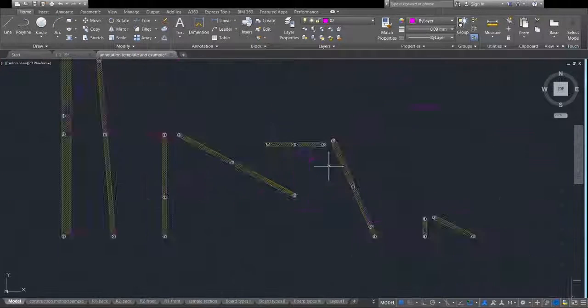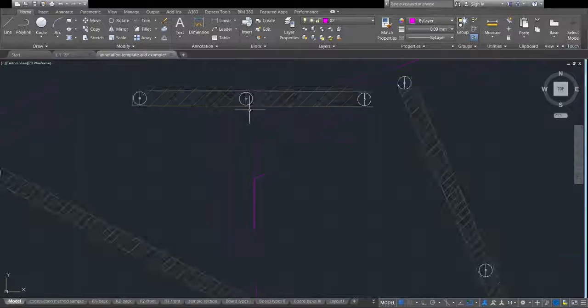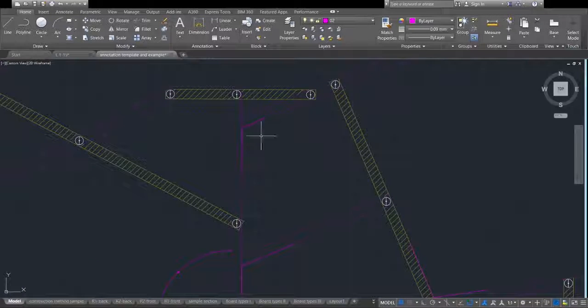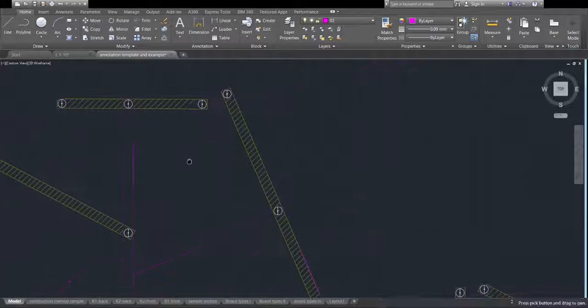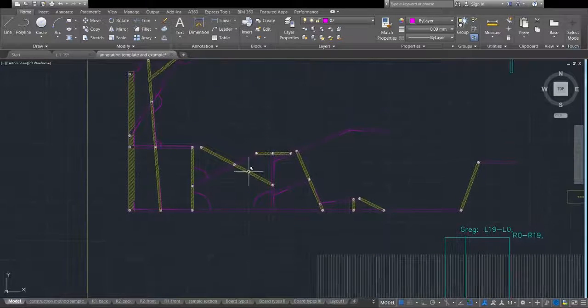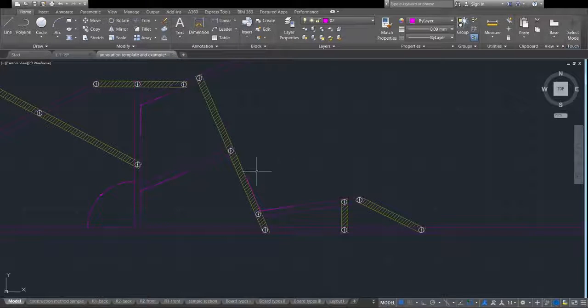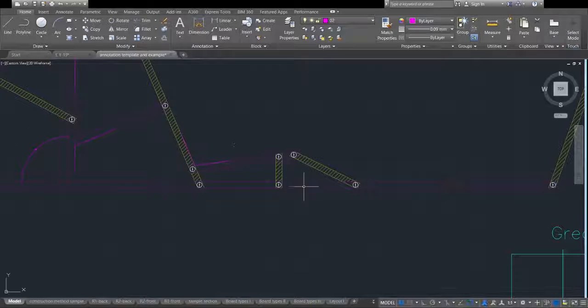Also, if you're dealing with a joint like this where there's an obtuse angle and an acute angle, it's going to be better to mark the obtuse angle, because that's just easier to measure on a mechanical level as well as on an annotation level. Generally, the obtuse angle is going to have more space to put an annotation in.